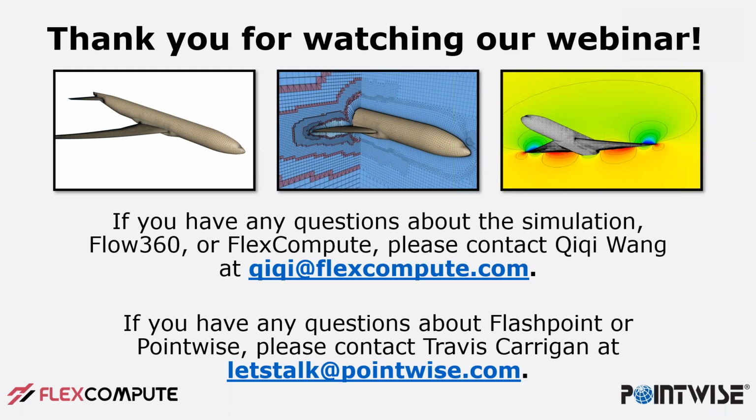And that's often more important because you want to refine to a certain turning angle, okay? Now you can change it after the fact if you want to explicitly specify an initial cell height. Again, it sets up everything for you, all of the boundary conditions. You can just go into the domain solver afterward, change that to the wall BC type instead of angle, give it an explicit value, and then reinitialize if you wanted to.